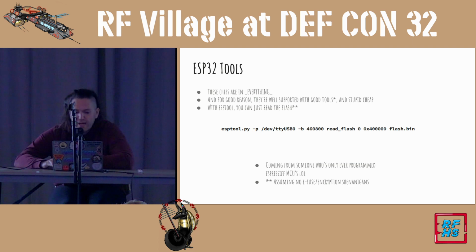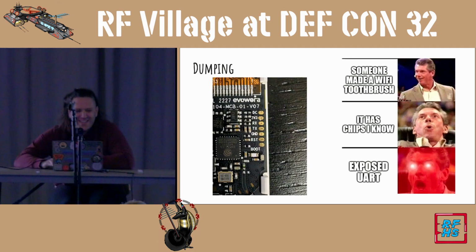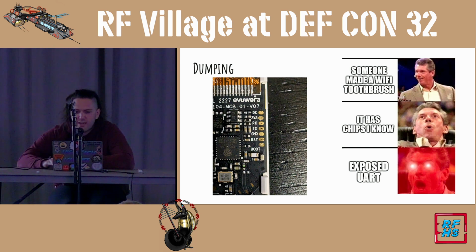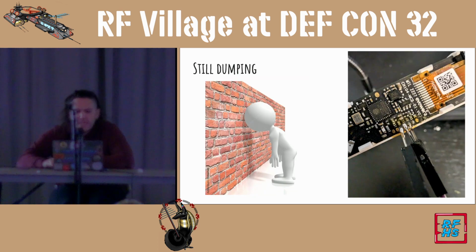So I went ahead and bought one, and it showed up. And if you can see over there, that is in fact serial UART that we have broken out there. So we've got the ground, 3.3 volts, RX, TX, reset, as well as boot. So the thing showed up, I took it apart, and I was very excited to see what I had found. And that's essentially when the trouble starts.